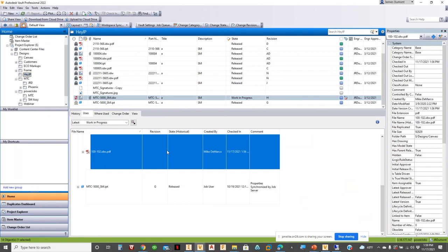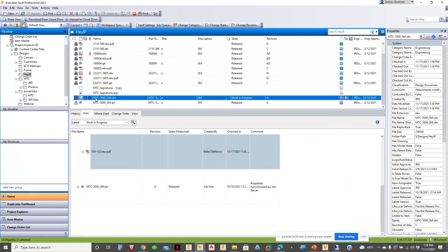So any file that's brought in, it could be a PDF, TIFF, JPEG, doesn't matter, can be brought into the system and added to the file so you have full access. You don't have to look in a folder to see if there are any files that pertain to this file. That little paperclip lets me know there are supporting documents, and I can see everything right there. You just can't change a file if it's released, it's locked, because adding an attachment is basically a bump of the rev. So yes, any document can be added to the system and any file can be attached to any other file.